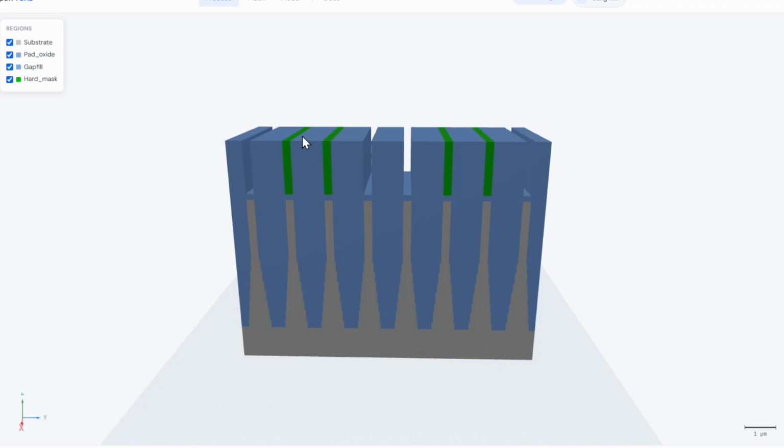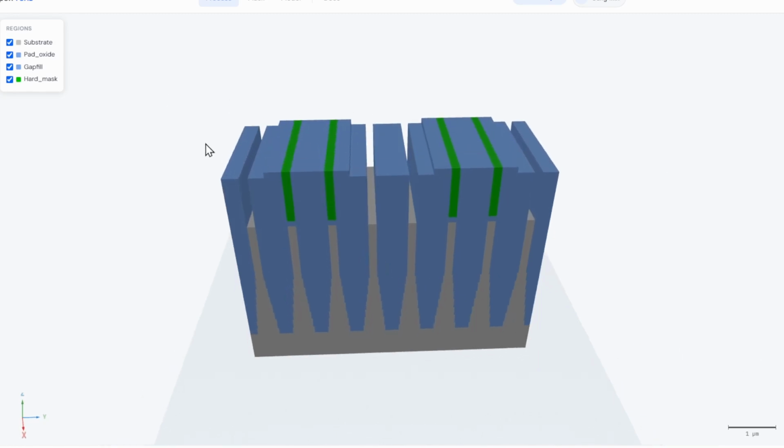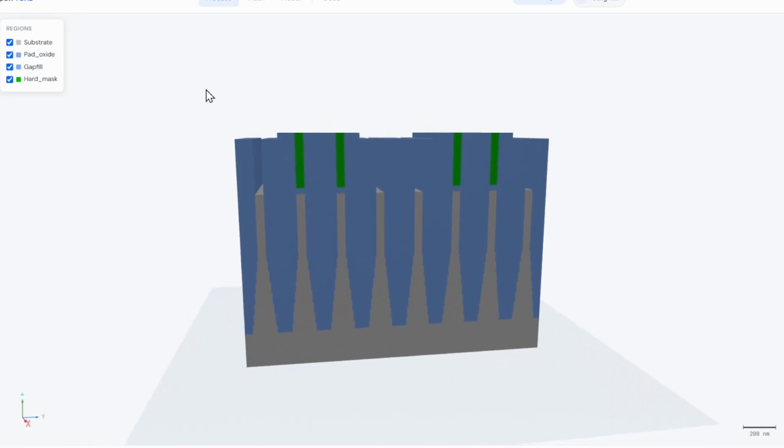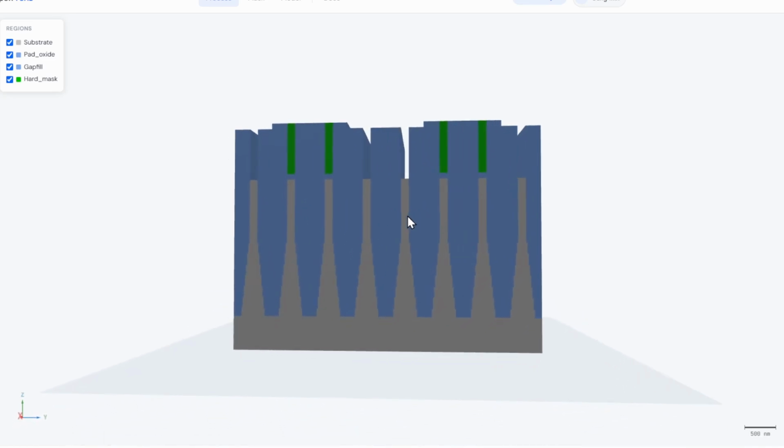So using the active mask, we save the active regions, but for the non-active regions, we etch the nitride. Subsequently, of course, we will also remove this fin. So let's have a look. As you can see here, we also simply etched the pad oxide. Now this silicon fin is exposed to the air.